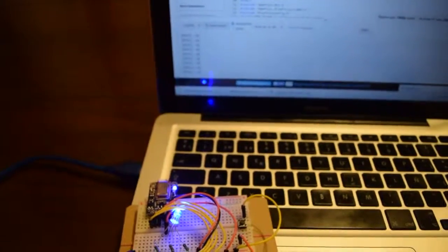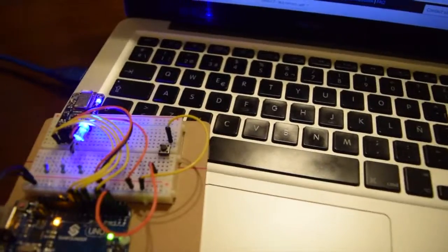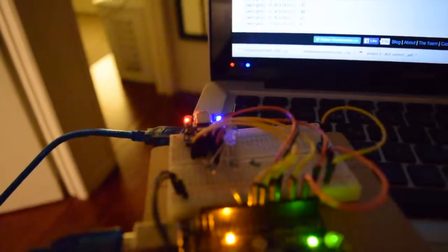I'm going to walk around with my laptop and the BLE card to move away from the phone, which I think is easier to show. So right now we can see the intensity of the BLE signal. The value right now is going 30, 90. The cutoff value is 90, but because it's taking 30 values, now here's the low signal, and I turn off the light.